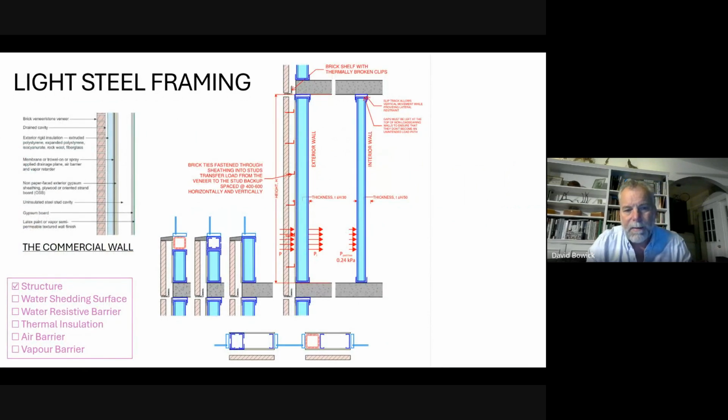So how do we deal with light steel studs? Similar to block from your perspective as the architect, because you're owning what the non-load bearing assemblies are, we use a height to thickness ratio. The thickness has to be at least the height divided by 30. So you can see that it's thinner than a concrete block wall. Your overall wall assembly is thinner if you use steel stud as your backup wall.